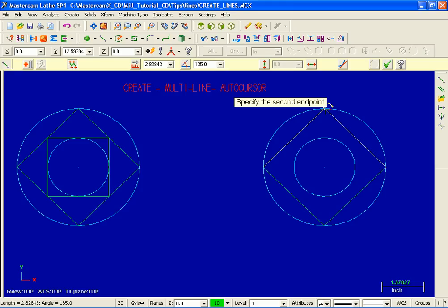Now in these cases AutoCursor uses a specific order to detect and snap to points. The order starts with point entities, then endpoints of curves or lines, then it moves on to midpoints, and then next it moves on to quadrants. So what's happening here is I only have quadrant and endpoint turned on, but endpoint is closer to the top of the list.